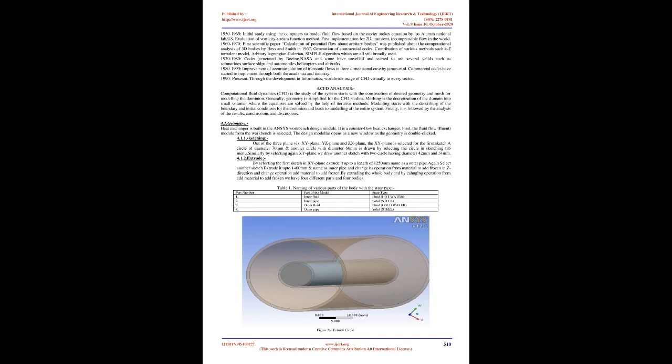Reynolds number. They observed that for a Prandtl number less than 2, the use of fins may not be justified because the increase in pressure drop is more pronounced than the increase in heat transfer. At a Reynolds number of 1000 and a Prandtl number of 5, the heat transfer increases by a factor of 3.1 while the pressure drop increases by a factor of 2.3.